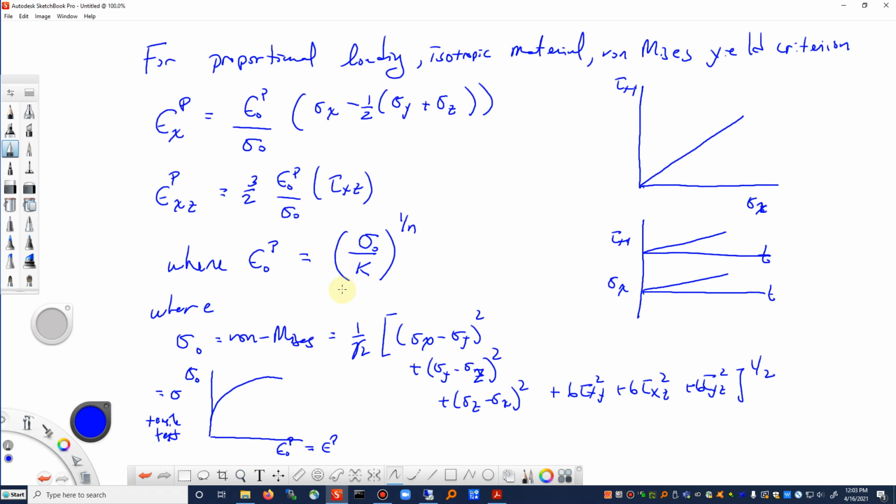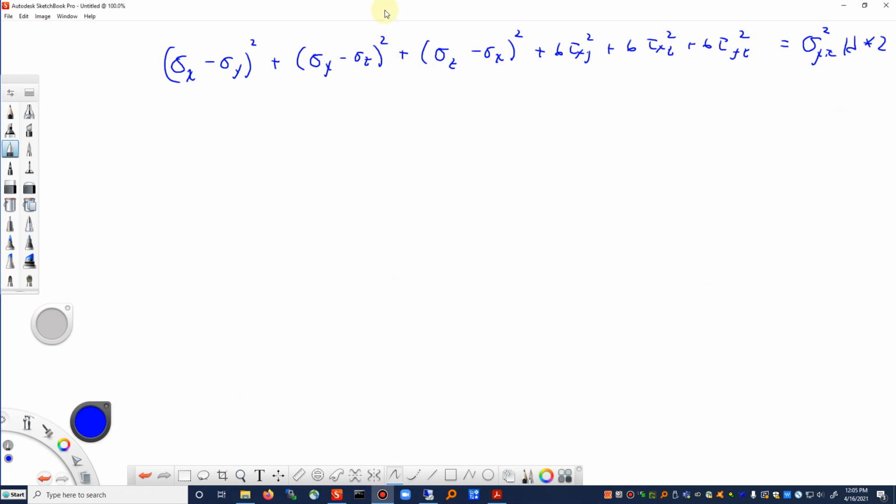All right, well, let's talk a little bit about the yield condition and the envelope that this plots when we take a look at the von Mises yield criterion, for example. And to see this yield envelope, I'm going to rewrite our von Mises equation a little bit differently. There are other yield criteria you could use, and they're just different formulas that are functions of stresses. The von Mises is very convenient for a lot of the discussion that we'll have, so we'll just stick with it.